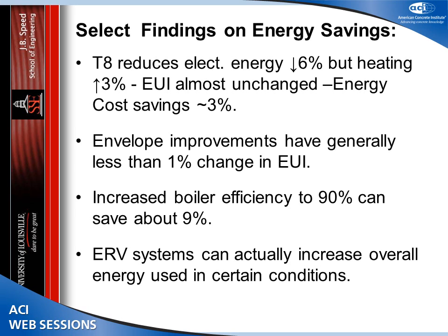And in deference to the previous speaker immediately in the first afternoon session, that's based on analytical performance, not on actual performance. We also got a significant increase by what I would call a fairly minor increase in the boiler efficiency, and not a very high cost one. We were able to get about 9% reduction in energy by increasing the boiler efficiency to 90%.